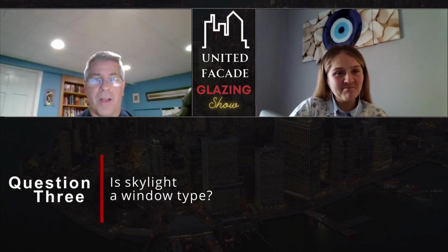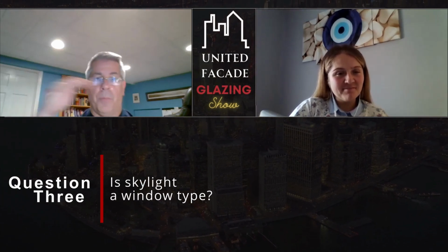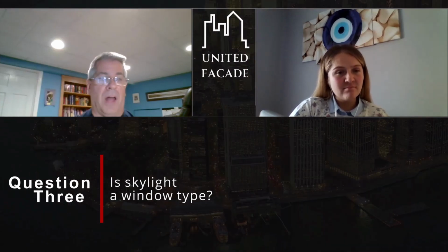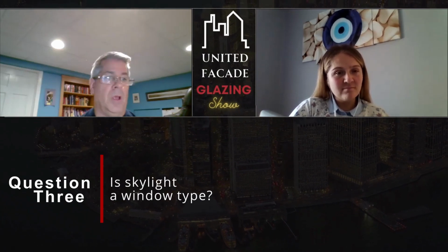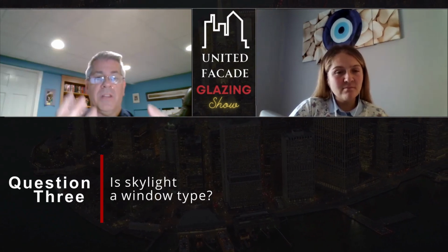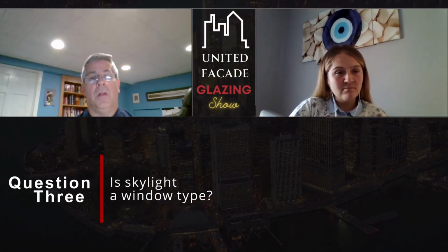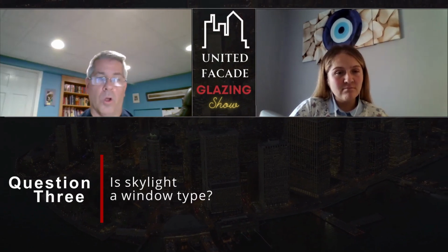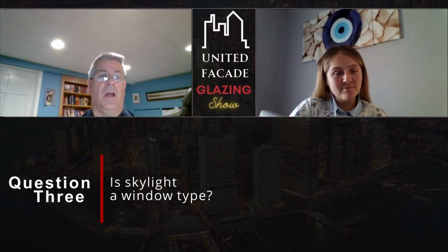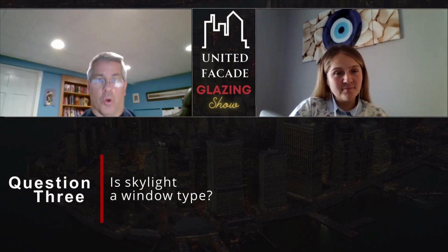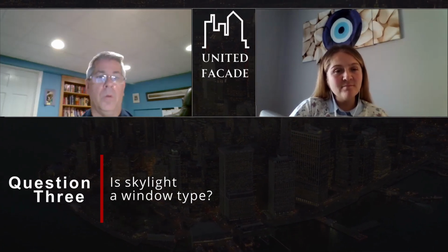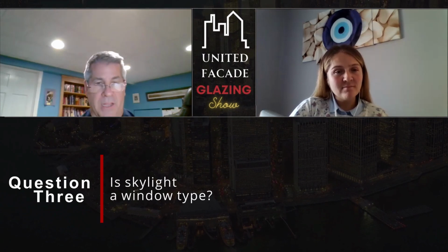What they're designing by us are walkable skylights, because up above on street level, people are going about their everyday business. You might have a plaza with picnic tables or planters, just a nice area in a courtyard of a building. But you need to bring light down to the area below. So they'll make walkable skylights. It's a very specialized skylight with obscure glass, so that you don't get a clear view from up above to down below, but you'll be getting the light coming through.